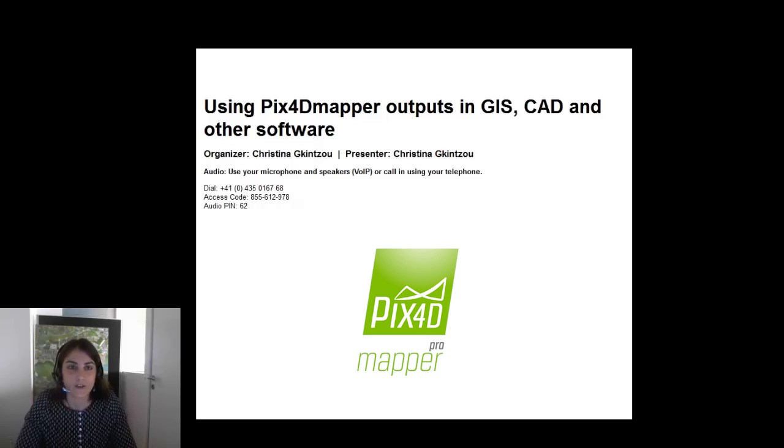Pix4Dmapper generates plenty of outputs. I tried to collect here the basic outputs, the core ones, the ones that the majority of our users use. Let's see, for example, the orthomosaic. If you are interested in 2D information, let's say you want to measure the width of a road or the width of a window on a facade of a building, then the orthomosaic is a very good output for you.